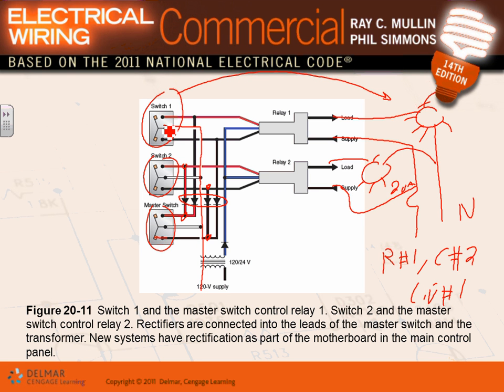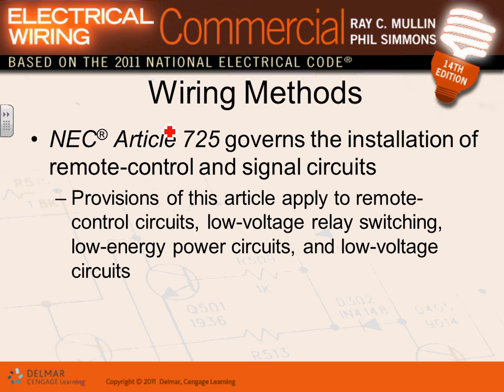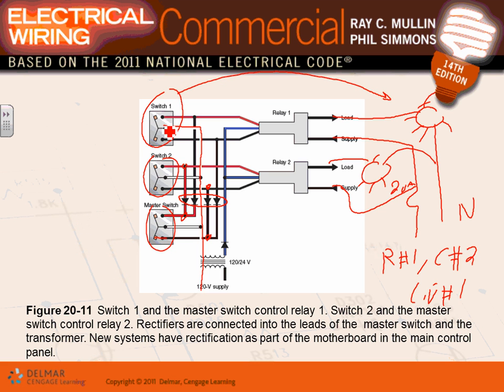Any comments? Any questions? So we have in our lab down, we have a wiring method, guys. You can wire these in our wiring lab. Okay, wiring methods. The wiring methods that we use with all these wires that you can see, can you guys see all these are low voltage. From here, this is called low voltage. These are class 2 circuits. Low voltage class 2 circuit, limited in the voltage, limited in the power.